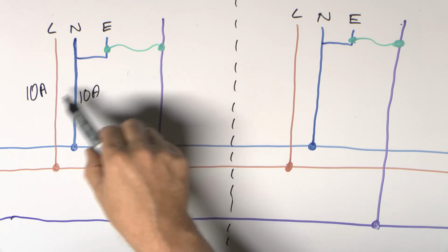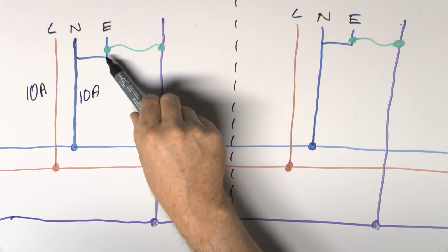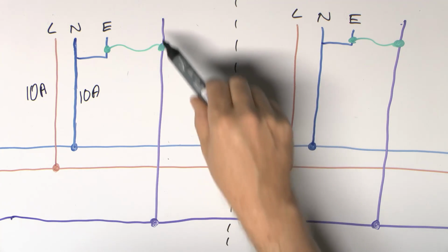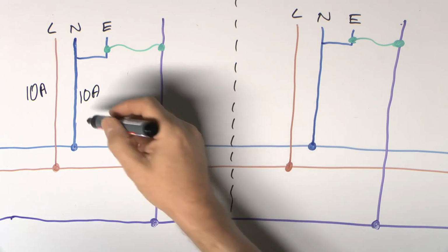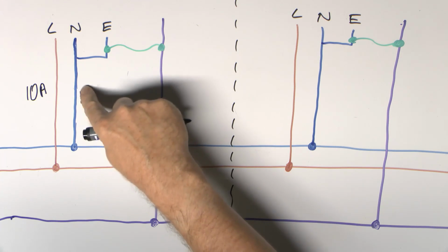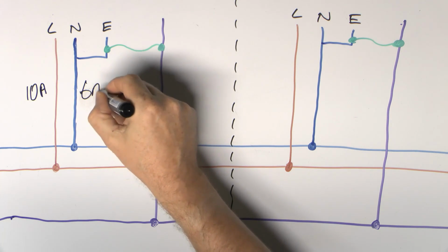And if we've just had these 2 conductors, that would in fact be true, but there's actually a problem here because we've got this bonding conductor going over to our nice solid chunk of copper here, gas pipe or whatever else, and that happens to be connected not only into the ground itself, it's also connected over there. So we're not going to be getting 10 amps here, we're going to be getting somewhat less than 10 amps there. Say it might be say 6 amps for example.